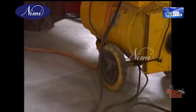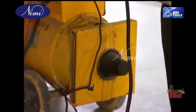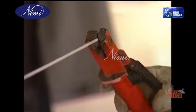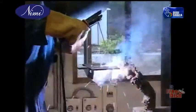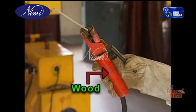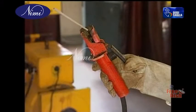The welding cable's end is always connected to the welding holder. This holder is used to hold the electrode in its jaws. It is made up of copper or copper alloys which have very high electrical conductivity. Now, in order to feed the electrode, a holder is a must. A major portion of the holder is made up of wood. This wood is an insulating material. If there is any electric leakage, it may save the welder from electrical shock.